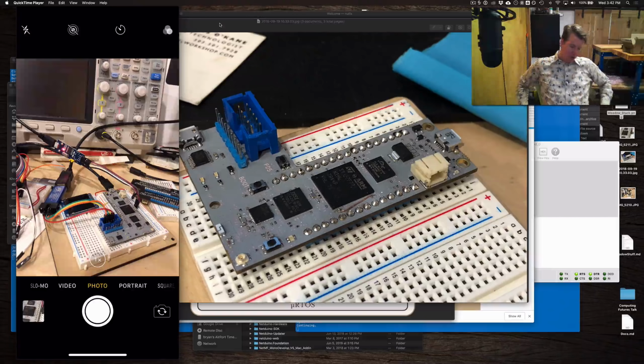A note about prototypes: it's a time-consuming process to rev a new prototype. Now, if we had tons of money, if you had the design on Monday, by Friday I could get in my hands the actual physical prototype. And that means doing a one-day turnaround on the PCB boards and then doing a two-day turnaround on the assembly of those boards.